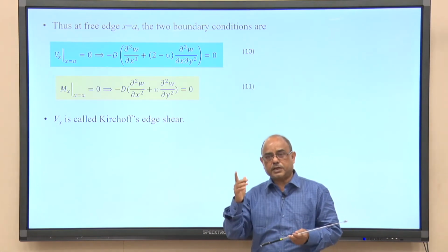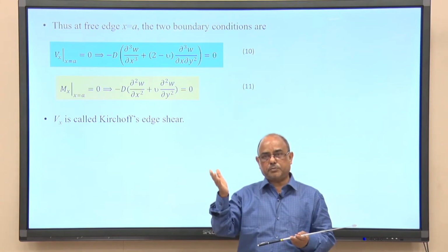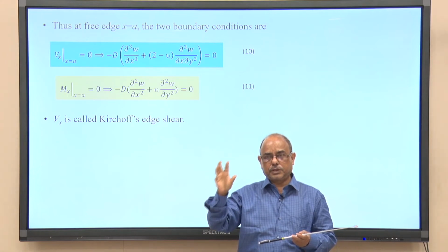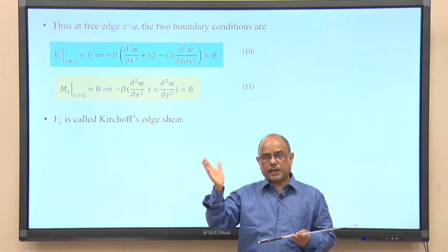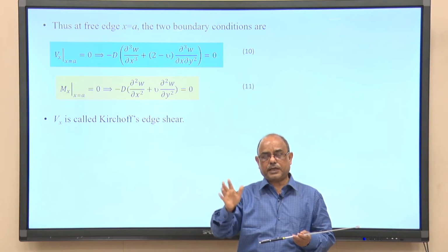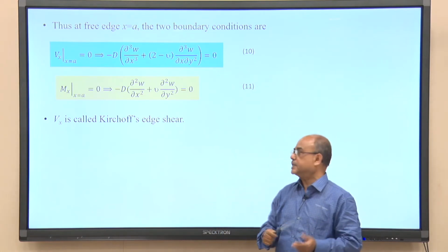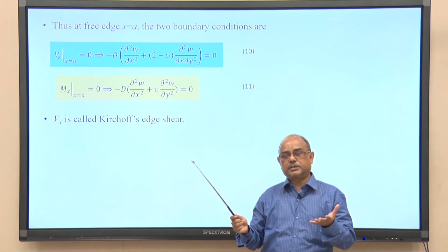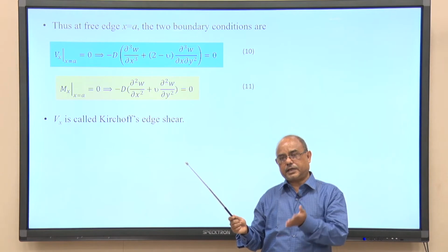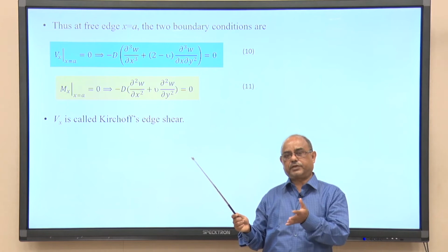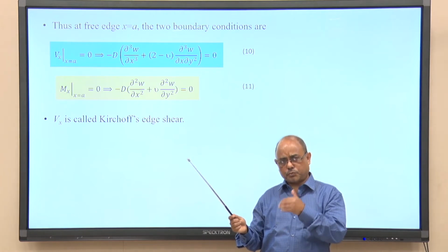In the simply supported case where the bending moment at x is equal to a, that edge was simply supported, we take it to 0 and then we neglected the curvature along the y direction. Okay. So, only del square w del x square was there, but here interestingly you can see, because it is the free edge, curvature cannot vanish. So, it is going to be deflected and free edge deflection will be measurable, significant deflection will be there at the free edge, slope will be there.